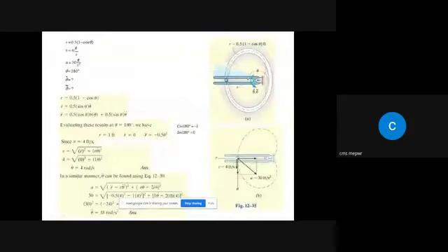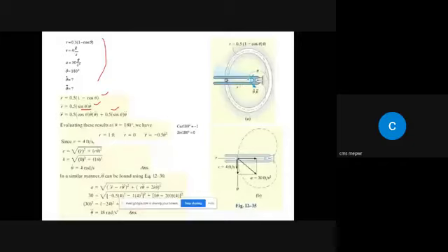So this is basically the given data. This is r, this is r dot, this is r double dot. The one thing that you need to do, for example over here, now we have two terms, so you need to use the product rule for differentiation, right? Yes, sir. Okay, so at theta equal to 180 degrees, put these values over here. Remember, cos 180 is equal to -1, sin 180 is equal to 0. So when you put, you will get the r dot and r double dot values.